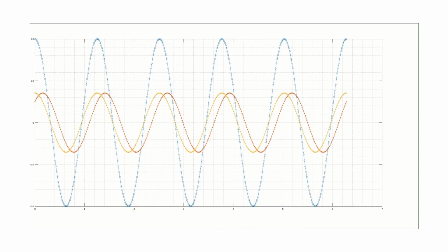Then here you see the one in the blue color. This is the input voltage. The one that is in the dark orange color is the current that you obtain using I equals V divided by the impedance Z. So you have this current which is shifted by a phase difference with respect to the voltage. And now the lighter orange or yellow here is the current that has been shifted by a phase difference of 0.7854, which we have calculated earlier. And here you see that this is in phase with the voltage, right?